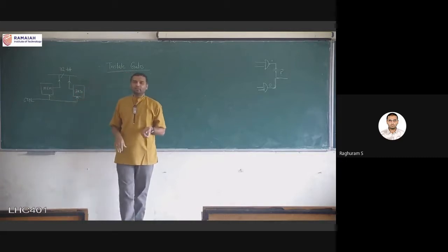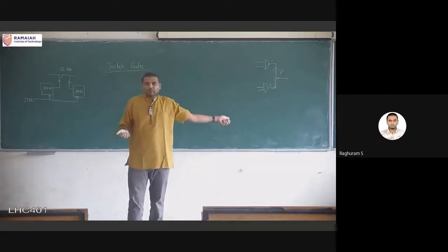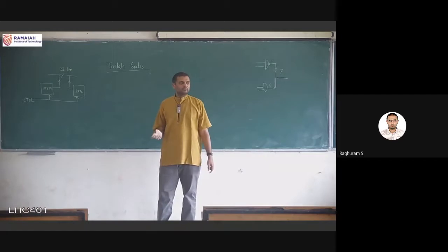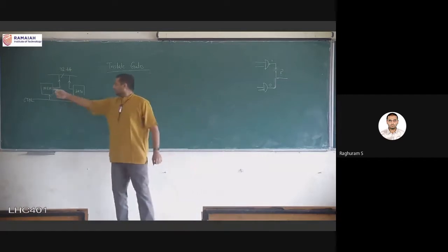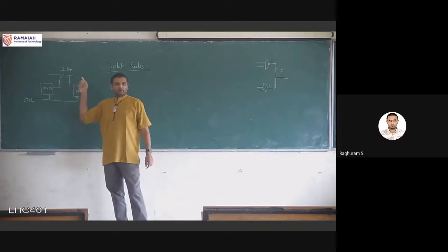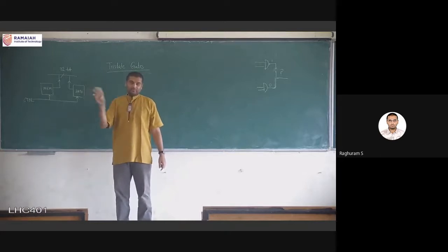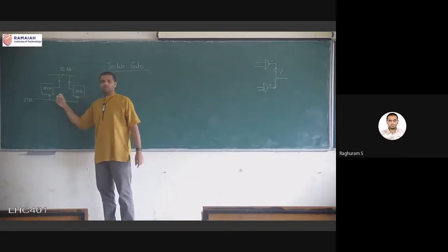You might have heard of this term before. There are multiplexers. This is a multiplexer, right? Here also is a multiplexer. The typical example for the buses in microprocessors is memory and data. Either the bus is carrying memory addresses or it is carrying the data. So to switch between one and the other, we can do it by means of a control signal.